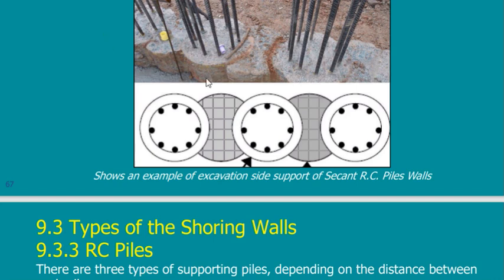When I put my reinforced concrete pile here, this will be very strong. Of course, this is just a plug. It is not strong. It cannot support the wall. The wall is supported on these reinforced concrete piles. But these are just plugs to prevent water from passing to the other side.